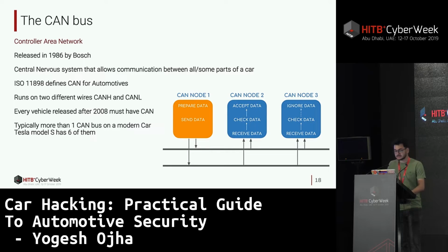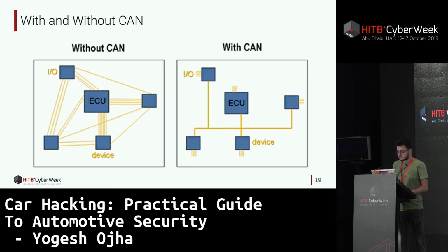The sensors and the ECUs have a transceiver that you see here. The transceiver is actually responsible for either accepting or rejecting the packets. The CAN node generally consists of 3 different components: a transceiver, a CAN controller, and a microcontroller. A transceiver converts the data stream of voltage from a CAN bus for other electronic units to understand, while the controller acts as a link layer between the nodes.